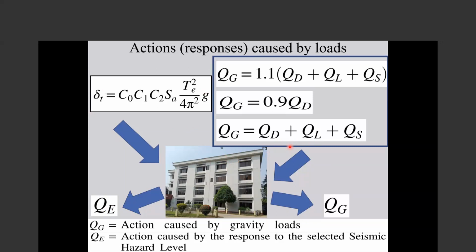If it doesn't reach, first we make sure that it's not a numerical problem. If there was no numerical problem, we say unfortunately the building can't undergo this level of earthquake. Because now when you look at this, you should just see a set of force control and deformation control parameters.